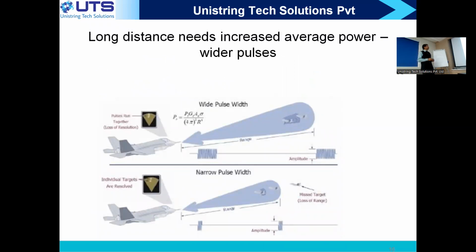Now, next, let's say for example, a simple philosophy. So far I've been focusing only on phase, time, frequency, wavelength. I did not talk about one important characteristic of a signal: power, amplitude, isn't it? Having understood that it is simple and you can easily visualize it, I did not focus much. But the amplitude and power of the signal is very important. And what matters is not the instantaneous power, it is the average power. I want you to intuitively keep this at the back of your mind.